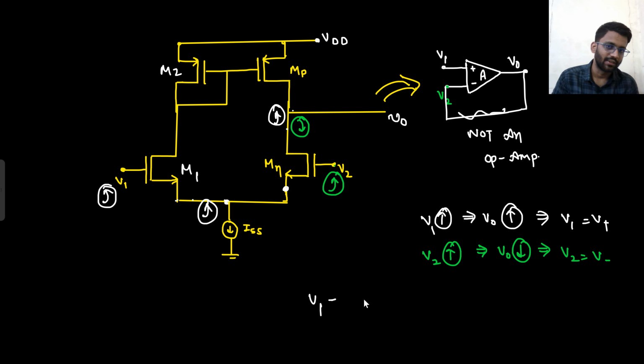The issue is output impedance. The gain is gmRD, right? And what is the output impedance? Gain is minus gmR0 and output impedance is R0, high, right? This was our common source amplifier.